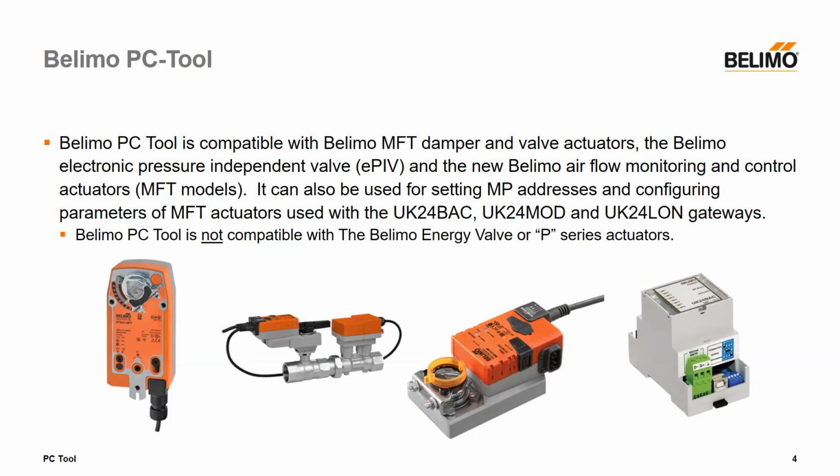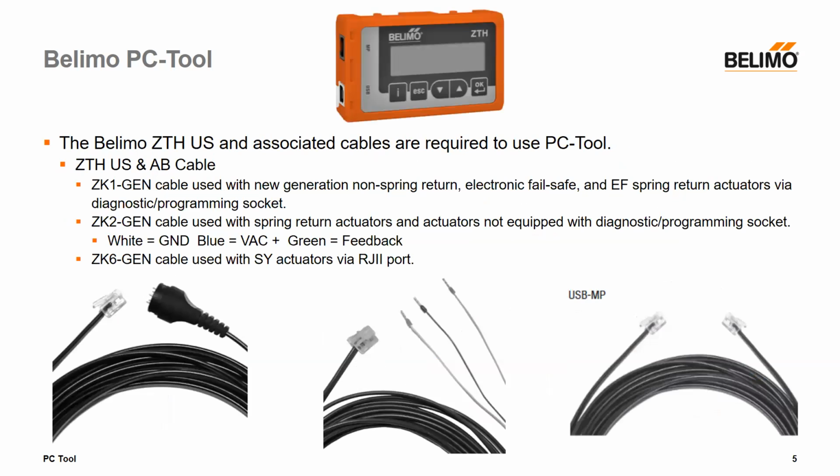With the energy valve, you will either connect to it just using a web browser, BACnet over IP or MSTP, Modbus, TCP, or RTU. So important to note that the energy valve and the newer P series actuators are not really designed to work with PC Tool. As I mentioned, the PC Tool is a software, and again, it's a free software. No licensing, no fees, nothing like that.